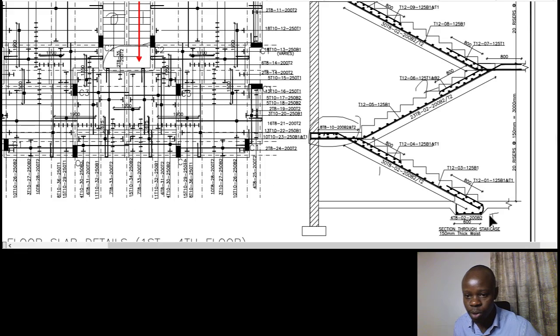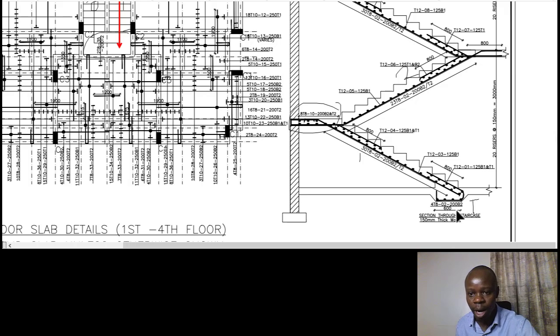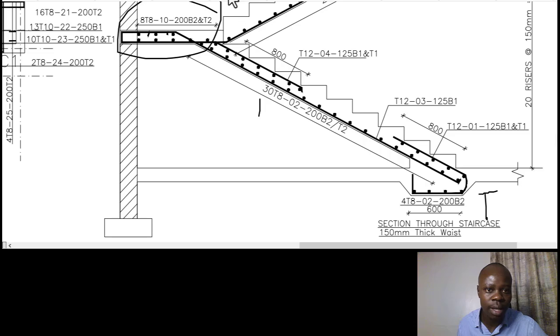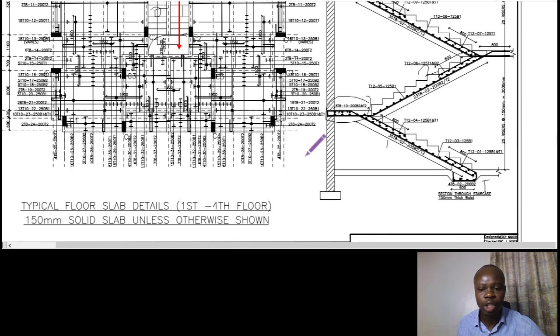First and foremost, looking at the thicknessing, the one that we've just studied, at the thicknessing point we have the reinforcement bars that are represented as tips. The tips normally mean, for instance, the first one is at these bars. The tip normally means that it's a section, and for that section it's been cut across, so that tip shows you that that bar is going the other way. It's going across, it's not going along at any point.